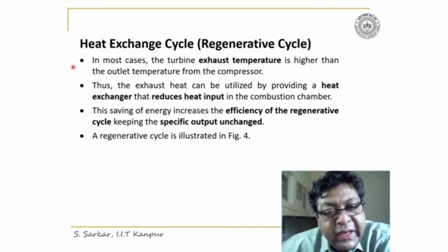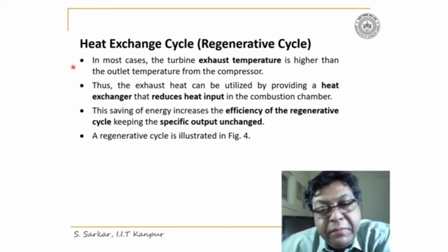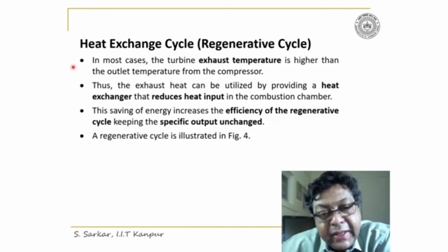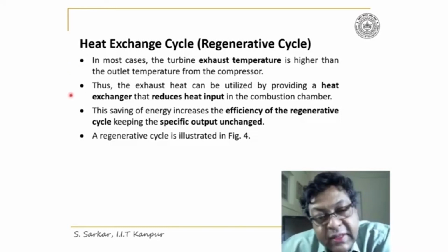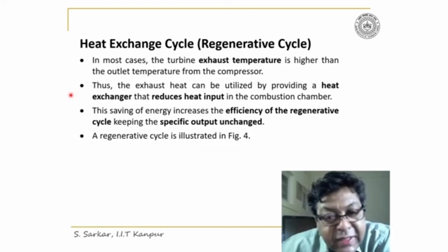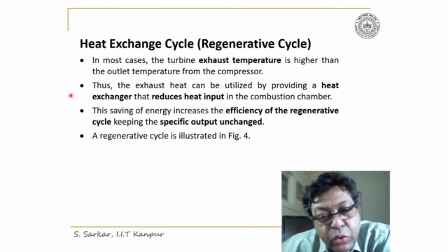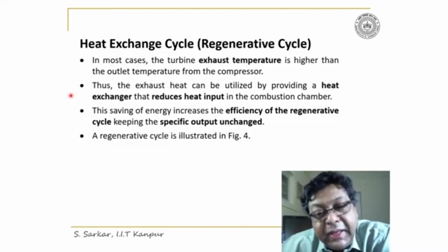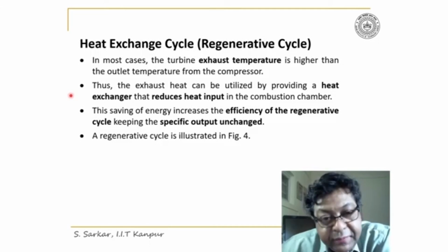In most cases, the turbine exhaust temperature is higher than the outlet temperature from the compressor. Thus, the exhaust heat can be utilized by providing a heat exchanger that reduces the heat input in the combustion chamber.